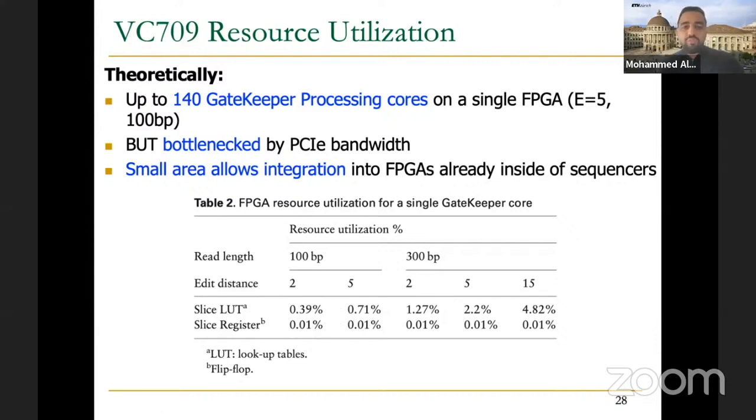That, of course, if the critical path allows for that. You may want to pipeline these problems together because the maximum delay you can have cannot achieve the maximum frequency you can use in the FPGA.